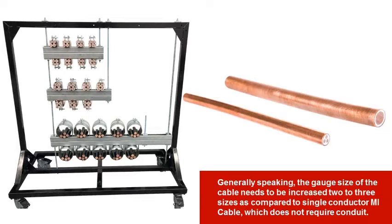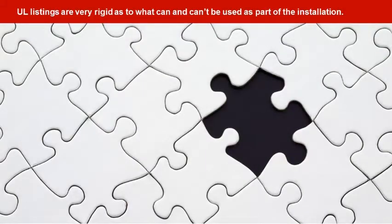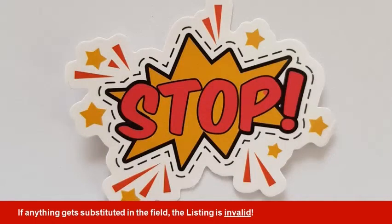There are also several other potential issues that must be addressed when considering a fire-rated cable option that requires conduit. Due to past issues with these type of cable systems, UL listings are very rigid as to what can and can't be used as part of the installation. For example, one can only use the specific manufacturer and brand of conduit that is noted in the listing. The same is true for the connectors, couplings, or boxes used. If anything gets substituted in the field, the listing is invalid.